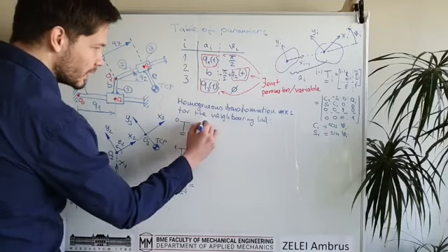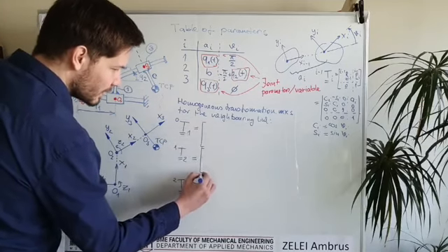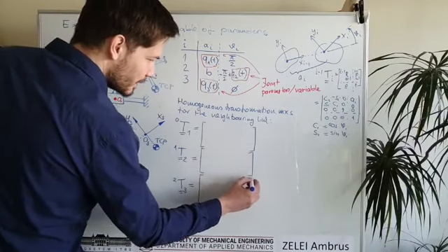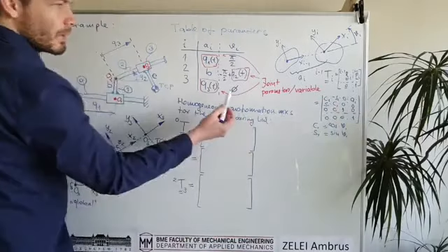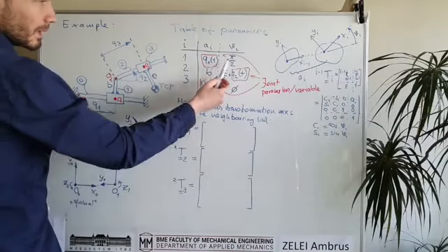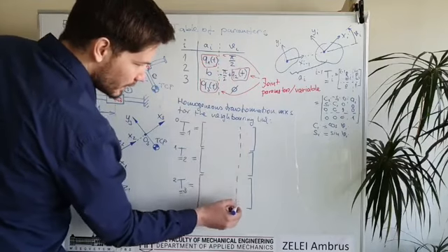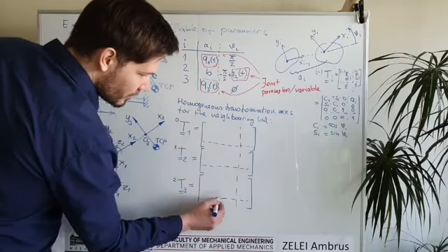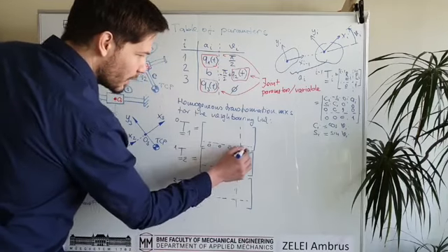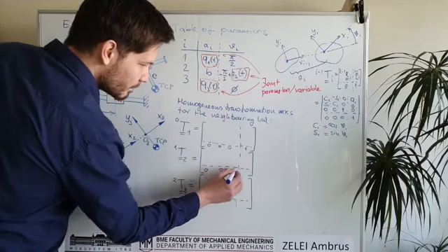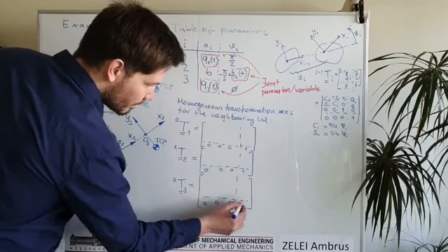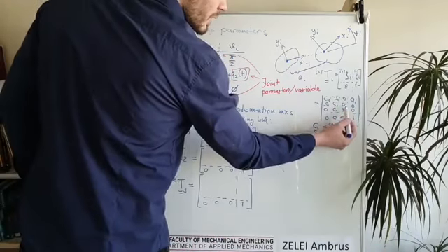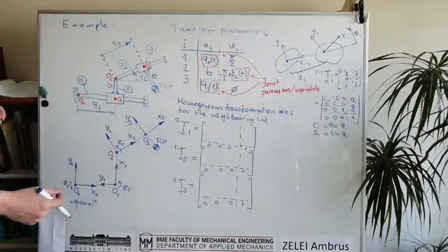So there will be 3 homogeneous transformation matrices, and we only have to fill them up based on this general formula and based on the value of the variables. And there is always a part which is not changing, so this is 0 0 0 1 in each case. And the other parts must be filled up. Actually this 0 0 0 1 is always the same, but let's go one by one.